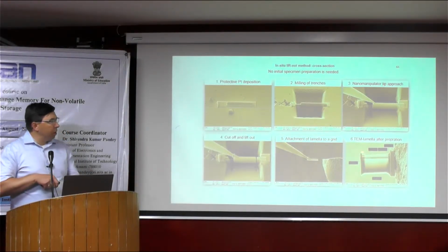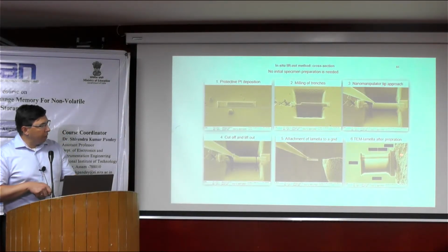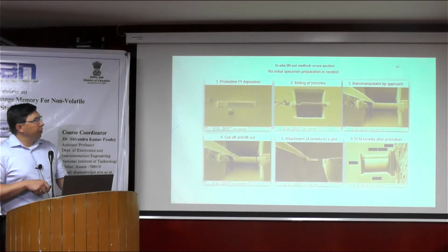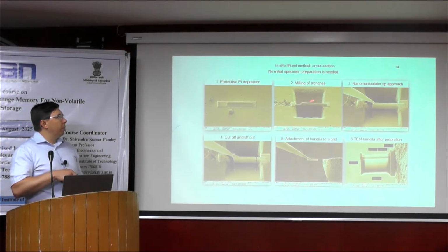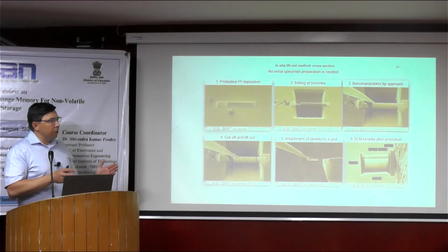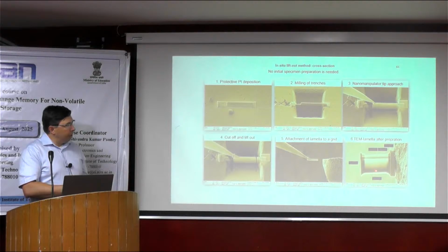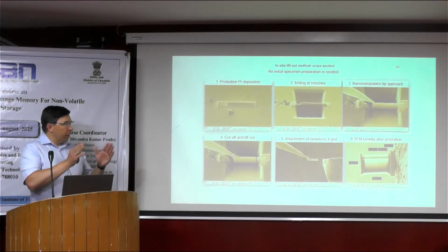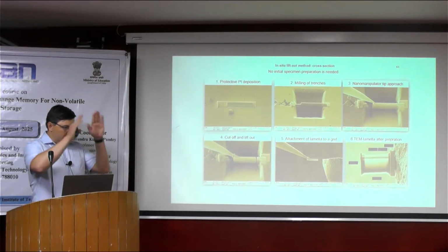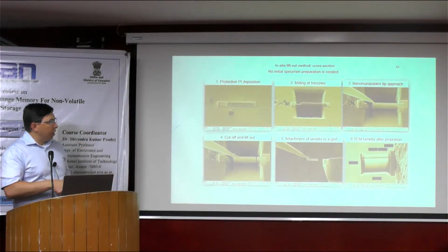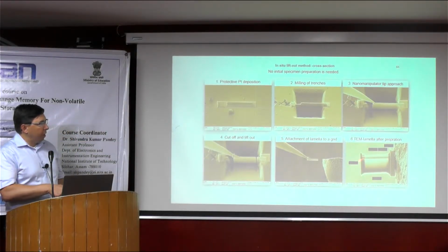Here you can see already some troubles with FIB preparation. If you make such trenches, your sample is like a wedge type. Here you can see that the thickness at the bottom is larger than at the top. So here this is much brighter, this is less bright. So you cut it like a trench, like in this direction. So at the bottom it's much thicker than here.